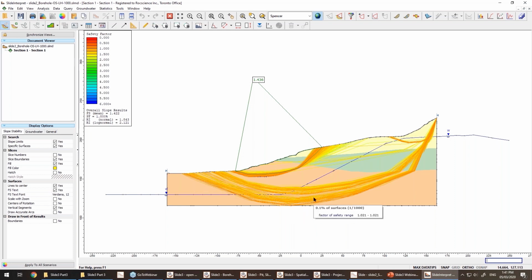This is called multimodal failure, and in all these limit equilibrium software packages, you only get the deterministic factor of safety together with its failure band. But in the future versions of Slide2 and Slide3, we're going to have multimodal failure, because most of the time, similar to this case, and especially for probabilistic analysis, one mode is not enough, and multimodal would be the answer.